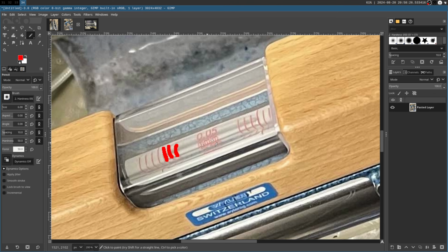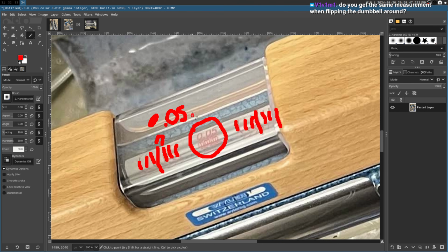If you can see these, there are basically 3 on each side of a center line for measuring the level. If you've ever used a level before, you'll be familiar with lines like this. Anyways, a singular one of these lines corresponds to 0.05 millimeters per meter, right? So 50 micron per meter is what this is measuring per division.